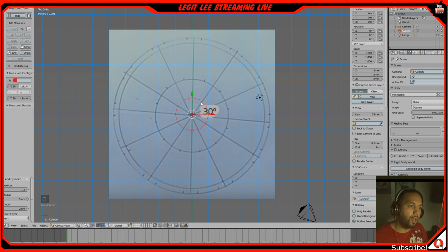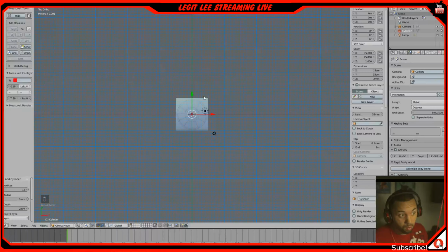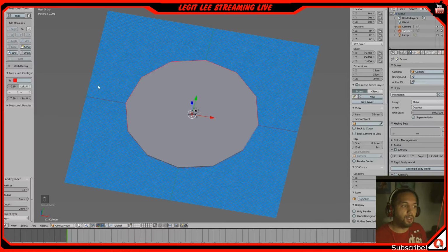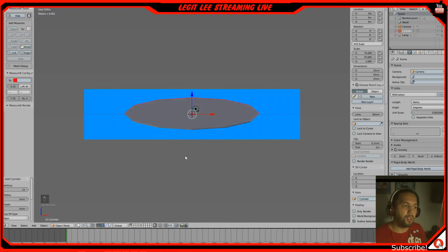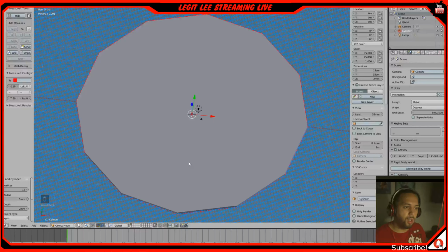So now we actually would be linked up with this information here. Now that we have 12 vertices, it went back down to 2 millimeters, so we're going to scale this back out again. We'll do 150 and 150. And there we have it. So now we're at 150. We can just zoom out. So now you can see this is the print bed size. It sits dead center. That looks pretty good. We have plenty of space to print this out with.